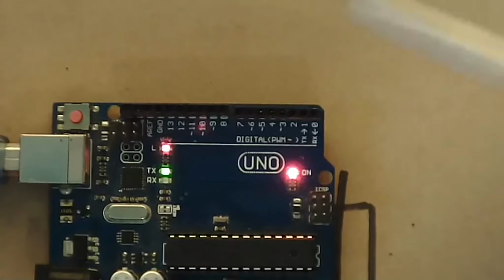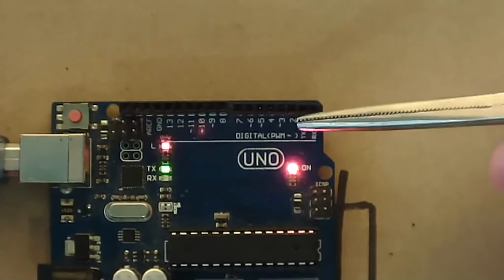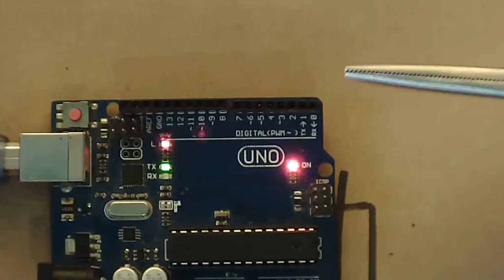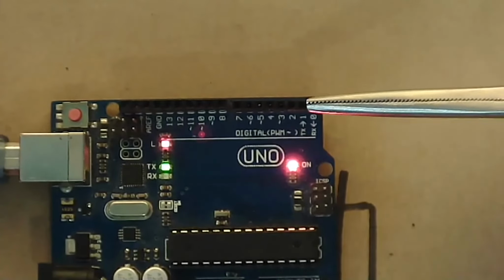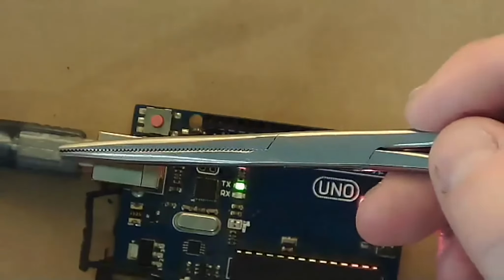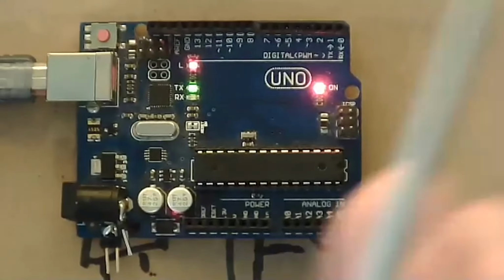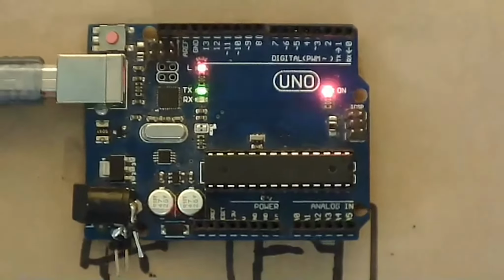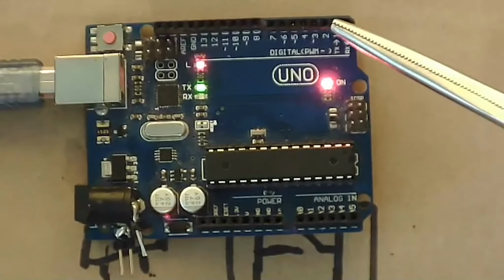And that's why if you're doing a project with Arduino, we want to just, in general, stay away from these pins for common use. Like we don't want to attach buttons or other components to these pins because that will disrupt the ability of the Arduino to communicate over its serial connection. So just general rule is avoid pins 0 and 1.